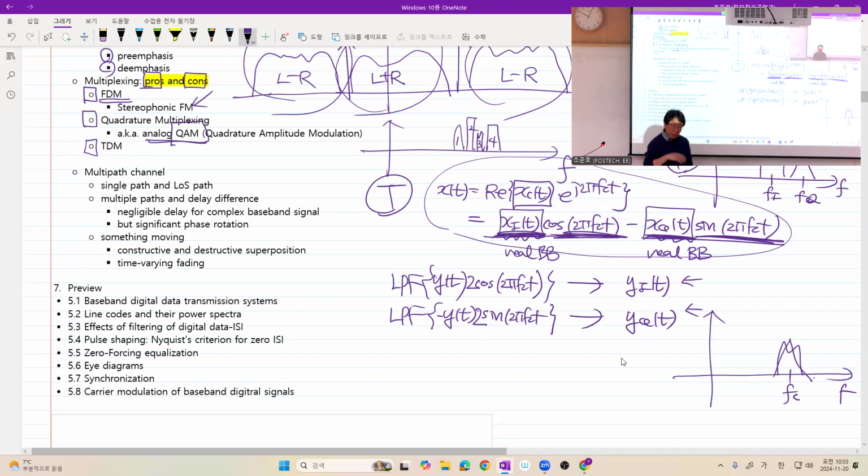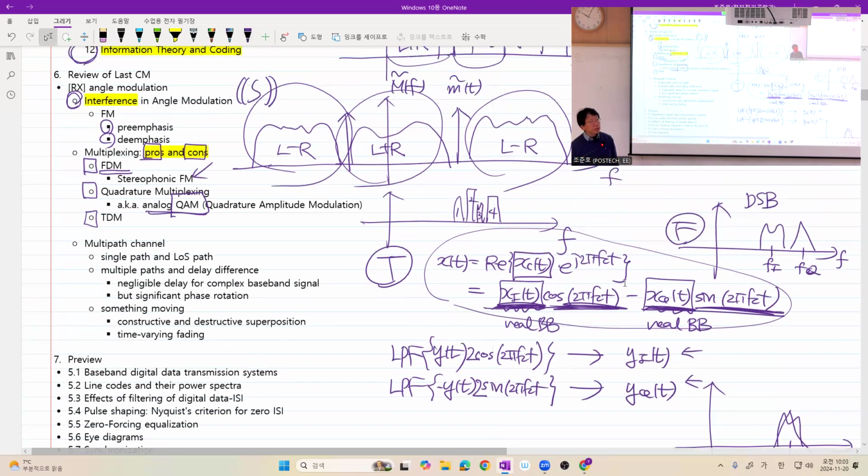However, in many crude receivers or transmitters, your local oscillators have phase noise. And phase noise may make the in-phase and quadrature components interfere with each other. So in order to have QAM work very well, you need a very stable oscillator, or if you cannot have that, you must be able to compensate for the phase noise to a tolerable level.